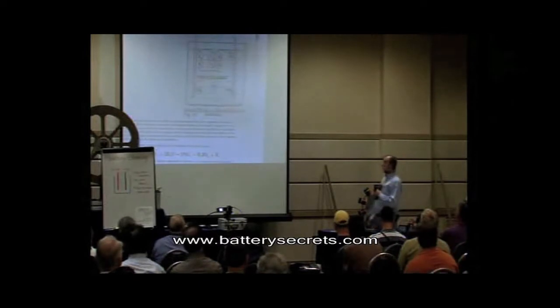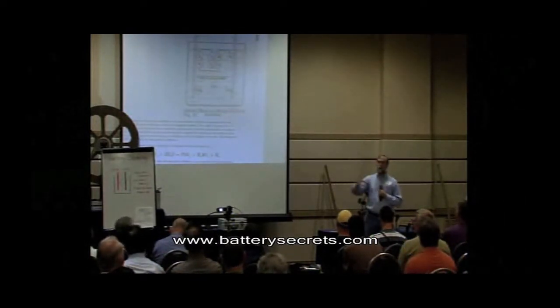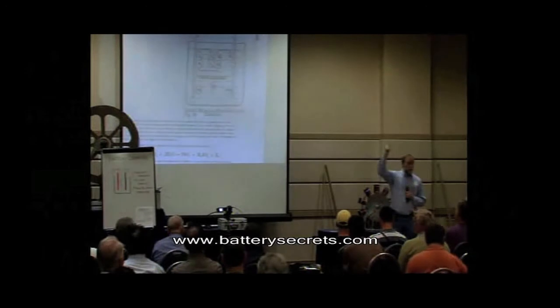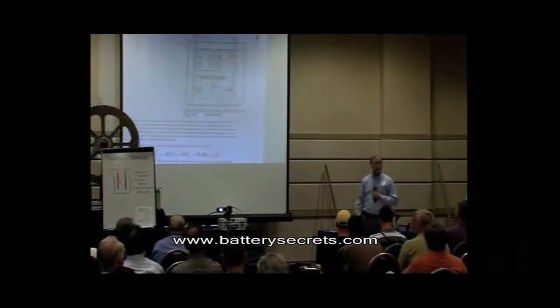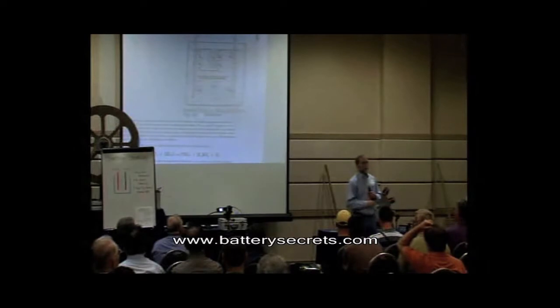So that's why these systems work. When you discharge an inductor, it creates that big voltage spike, gets that potential up. Or the other way that John's doing it is charging up a capacitor and dumping it down on it at maybe twice the voltage. But then, after you deliver that pulse, you wait.